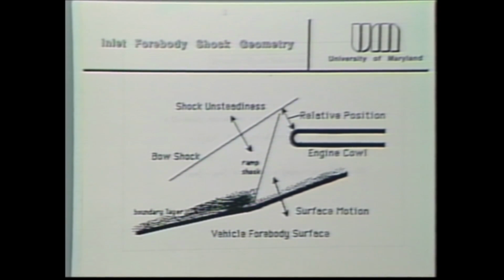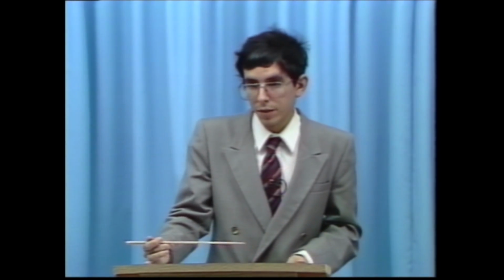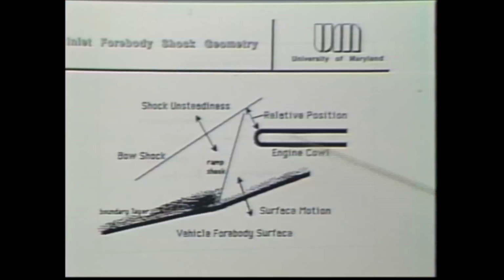The important range is going to be the mid-frequency range, say in the 10 to 100 hertz range. That's where we're going to expect some oscillations, perhaps from engine-induced oscillations. That can't be approached from either the quasi-steady solution or the high-frequency solution. And one of the conclusions that we draw there, we've done some computational modeling, and we found that indeed we can see some dramatic motions of the shock, whip-like motions of the shock in those frequency ranges. And that's also something that must be considered. Shock on cowl will be very difficult to accomplish in a steady state scenario.